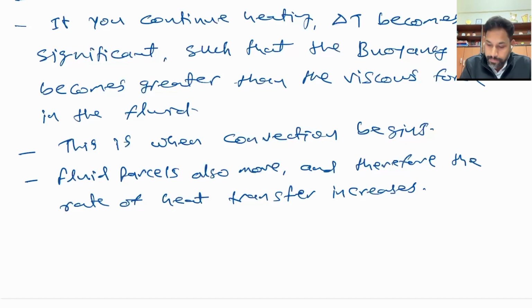Compared to conduction. And what exactly is happening in case of convection? You are having higher buoyancy force compared to the viscous force. So now if you want to quantify this effect, beyond which point conduction will be there and beyond what point you will have convection, for that we need to achieve a certain temperature difference. Only beyond that you will achieve convection.